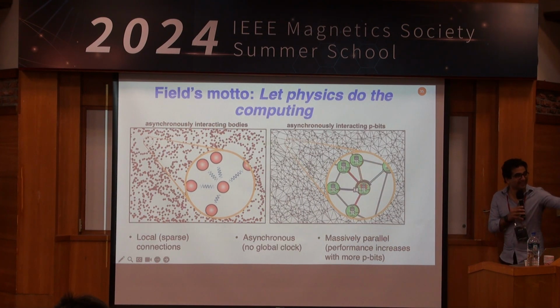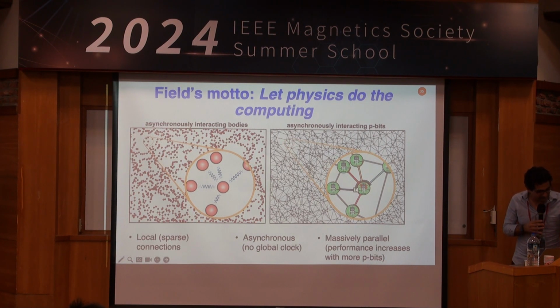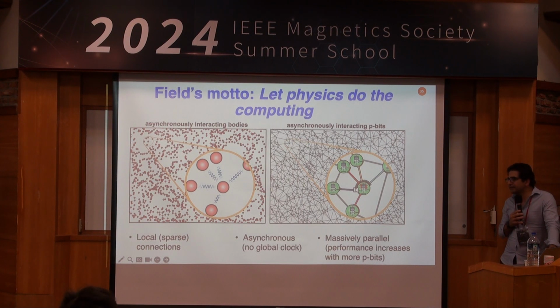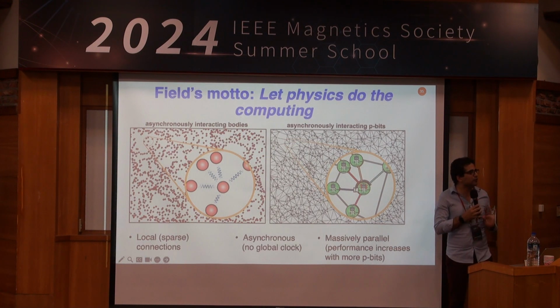Okay, thank you. I'm curious about the operation of the MTJ. You say the thermal stability factor is very small, so that the magnetization direction will change with time, and I'm wondering if a write current is needed, or if it just changes with time so we can detect it. No, in this case there is no write current, because all you want is the world's worst memory device. You want it to flip states all the time and be insensitive to write currents. You just want a random number that's unaffected.